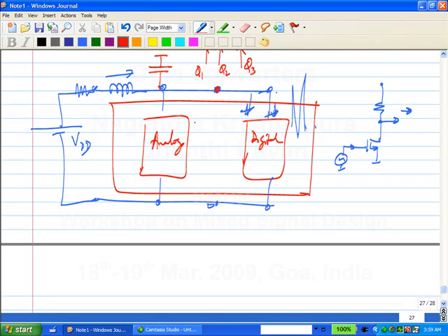All the high frequency current comes from the capacitor. Correct? Okay. Everybody is familiar with this? Decoupling or bypass capacitors? Okay. But whatever you do, finally there will be some jump on the supply. You can only reduce it. You cannot eliminate it. So, obviously in very sensitive circuits,